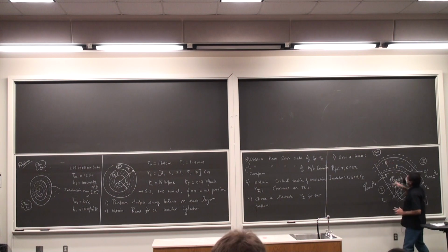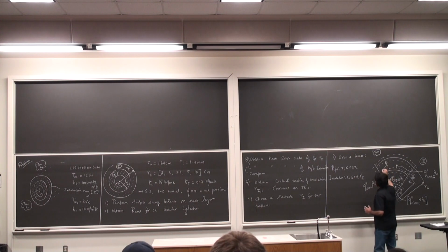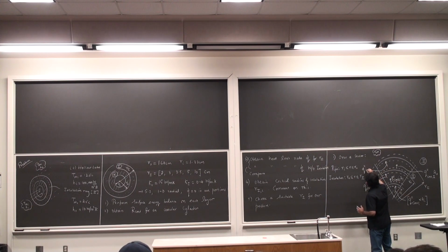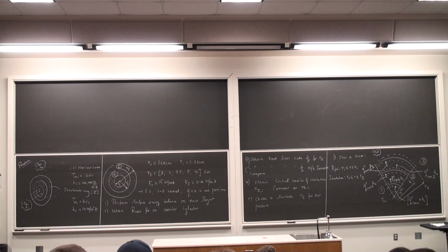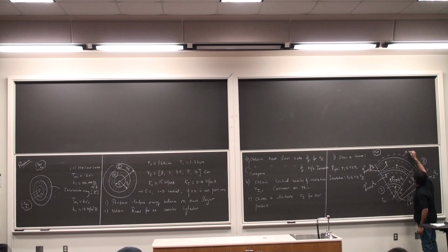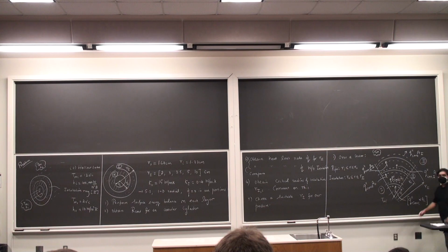No energy generation within the insulation ring, so this arrow is just going to radially travel along with the same flux value, and so this is going to be Q double prime conduction insulation multiplied by A suffix I, which is the surface area at the radius R suffix I, and then obviously this is going to come out as Q double prime convection out times AI. And I'm going to write all of these things.